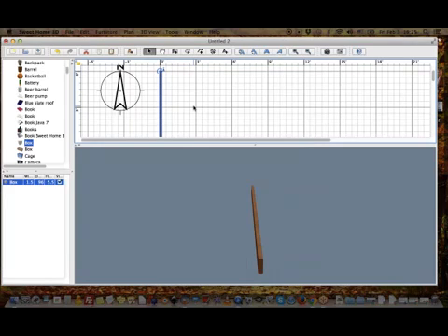Now, I am going to design my wall module as if it was laying down on the floor. And I do that for two reasons. One is because I find it easier to work on the X and Y axis. It's just easier to see it on the plan because this plan is two-dimensional. If I build in height, it becomes at one point really hard to see all the parts. And the second one is because wall modules are typically built on the ground. So I'm seeing it and designing it as it's going to be built. So that's really helpful.